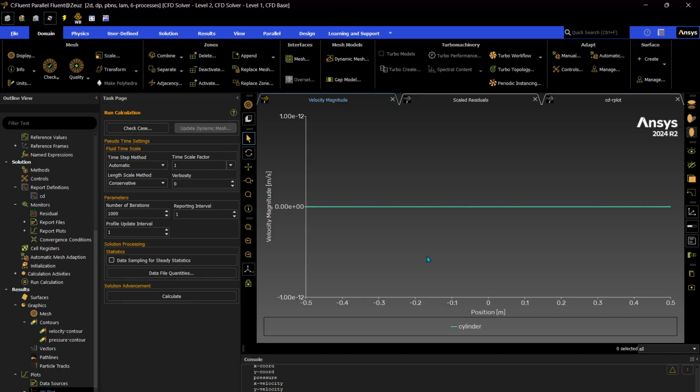We always assume that in a viscous fluid, on the surface, the velocity of the fluid will be 0 relative to the object in question. This is because of viscous forces acting on the surface, and essentially you would have molecules pretty much stuck on the surface of the object. That's why you have a velocity of 0, and this will be expected in the turbulence model as well. There you go. So yeah.